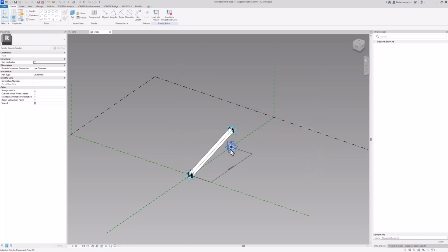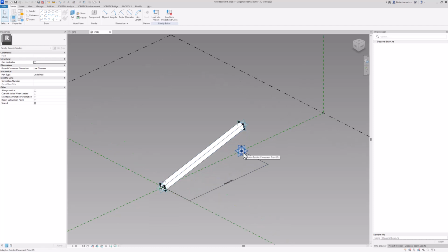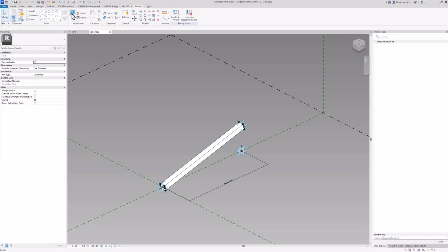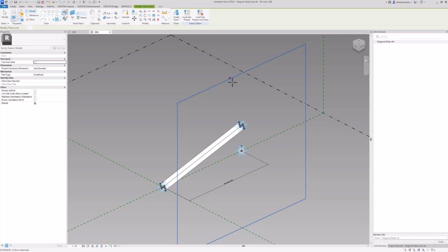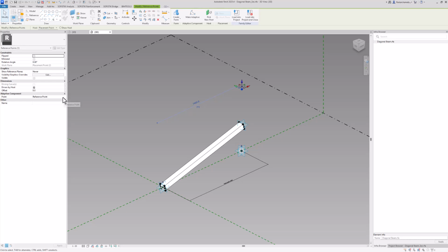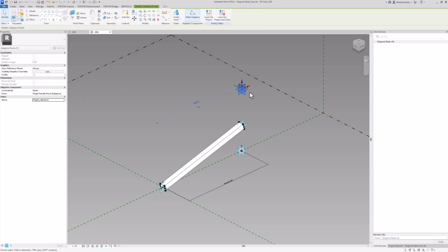What do you need to consider to properly assign a secondary axis to be read at the end of your adaptive family? Select any kind of point, it doesn't have to be in the plane or anything, and instead of leaving it as a reference point, you set it to a shape handle point. It is imperative to give it a name. So in this drop down here, I will call it height reference. It has to be a clear identifiable name for you because this one will also be available later in your cross member selection to be assigned to an axis.